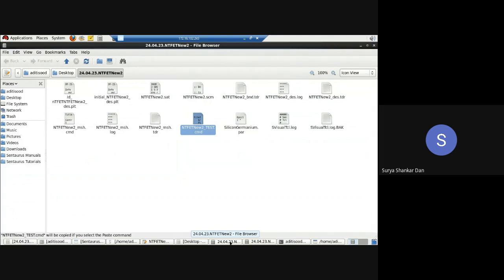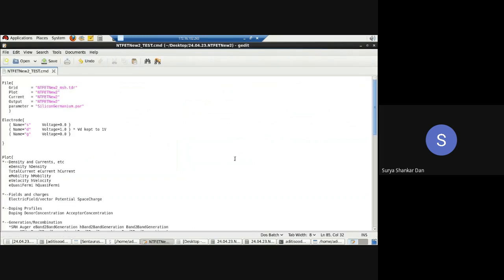We have discussed this in detail in the Physics and Modeling of Microelectronic Devices (PMMD) course. Silicon germanium is a strained silicon, so with the strain, the mobility increases. It is a well known and established fact that if you introduce strain in the silicon material, the mobility improves, and hence in the expression mu n C_ox (W/L)(VGS minus VT) whole squared, mu n increases.